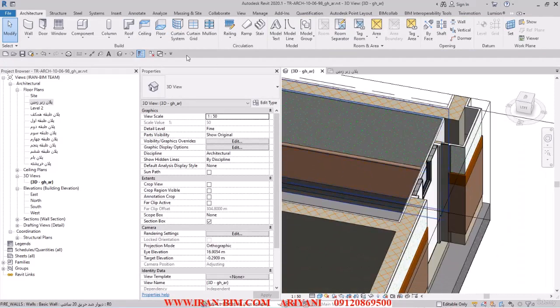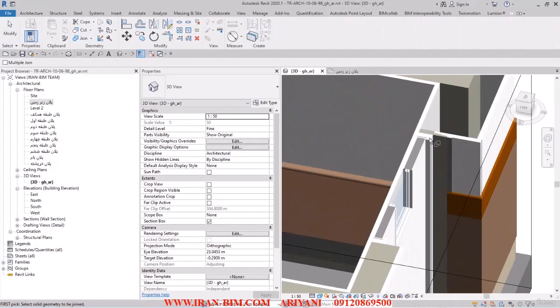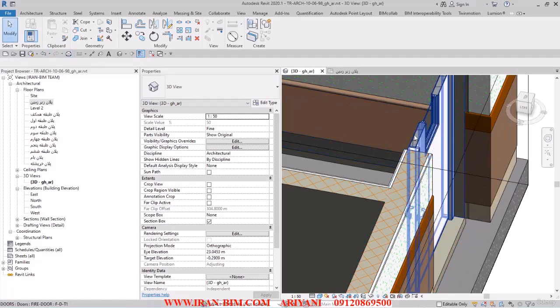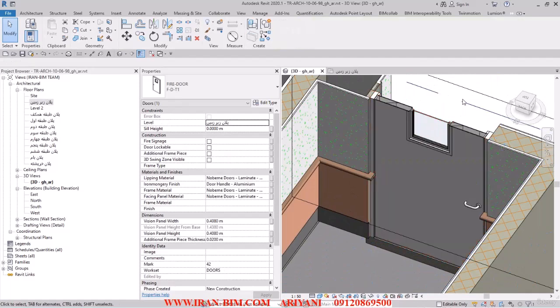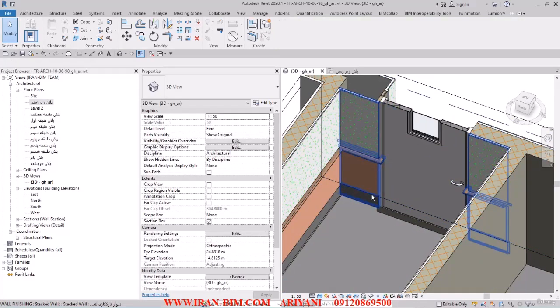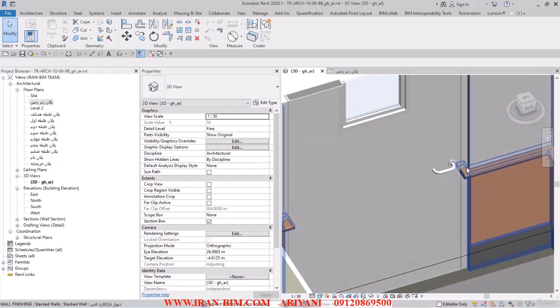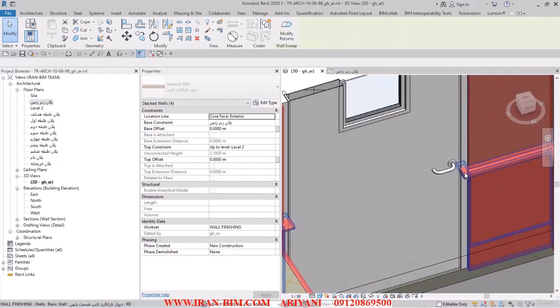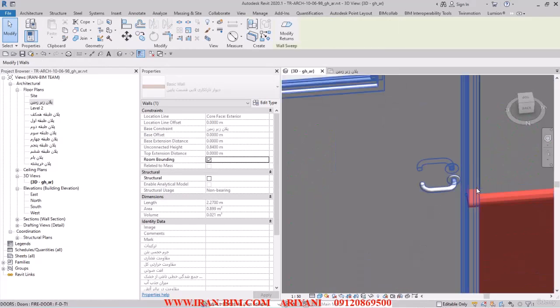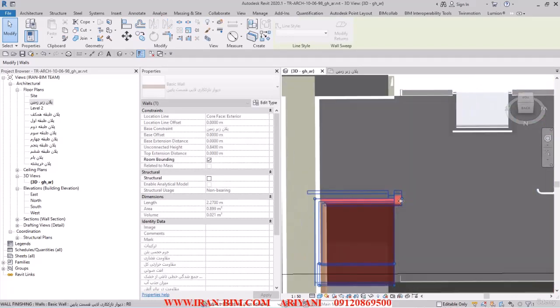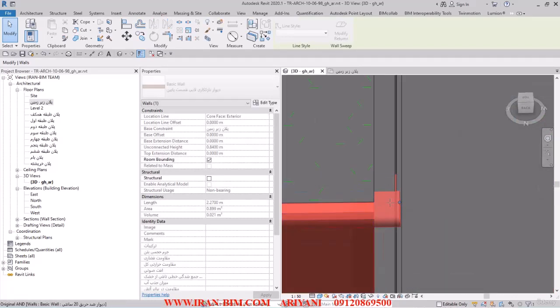Let's just zoom in so you can get a better look. And there it is. And then from the modify tool here, I'll select join. And then I'll join these two parts, the joinery and the framework. Let me just go here. And there it is. Let's turn this around, zoom in a bit, and it's this one right here. So right here in this area, I can just select this and manually move it to this point here. And then on the other side, I'll do the same and pull it to this point. And it just gets a better look.